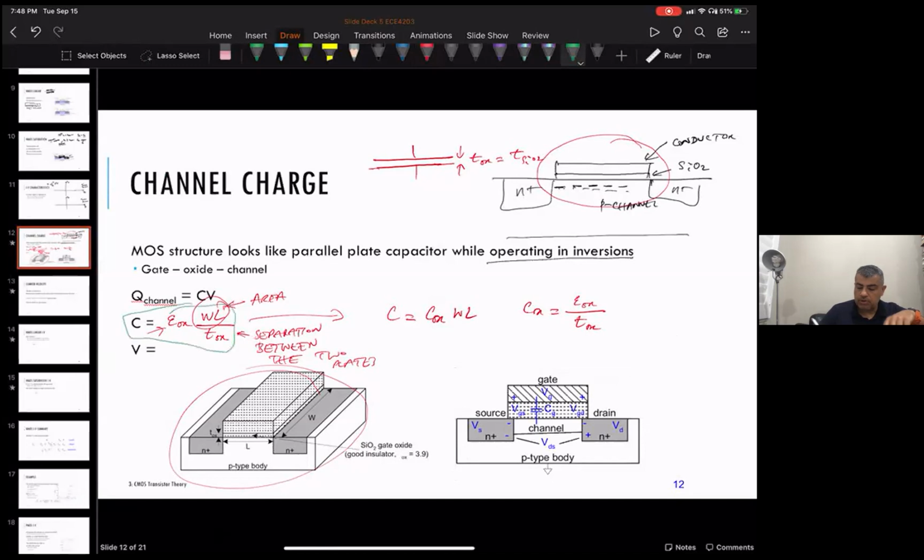This is the equation for a parallel plate capacitor, but when you're doing a design, you don't want to pull up epsilon oxide every time. You have to go look up these constants, which are funky numbers with lots of digits and scientific notation, and the thickness of the gate oxide is constant for any given process.